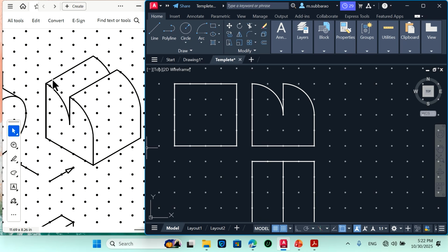The hidden surface boundaries: this is a line, but that line is coinciding with this, and this is another boundary line of the hidden surface, and that is coinciding with this. Another boundary line of the hidden surface is here, but that is not coinciding with anything, but we need to indicate it here. So the hidden line we need to show from here to here. So this becomes the hidden line, and that is actually the line between these two curved surfaces.